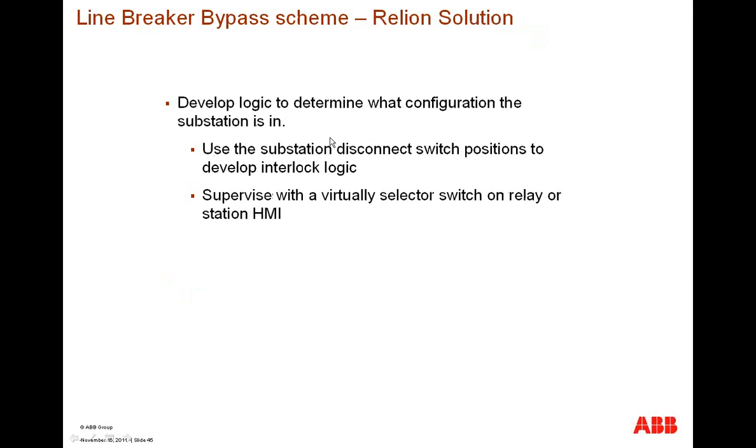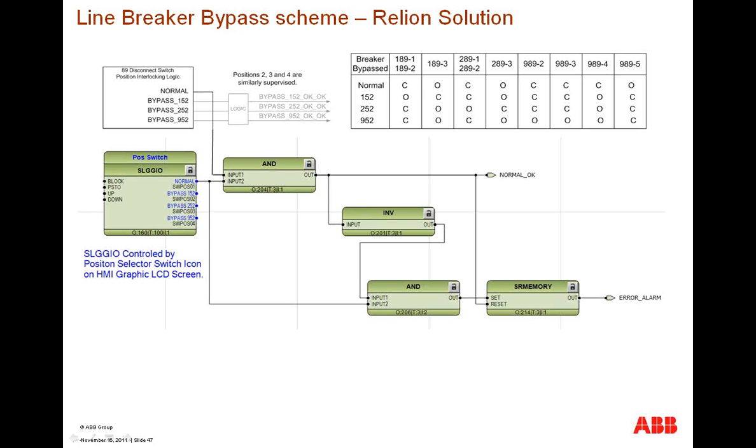So the solution is to develop the logic to determine what configuration the substation is in. Use the substation disconnect switch positions to develop interlock logic, and supervise with a virtual selector switch on the relay or the station HMI. So the logic used to develop this switching scheme.